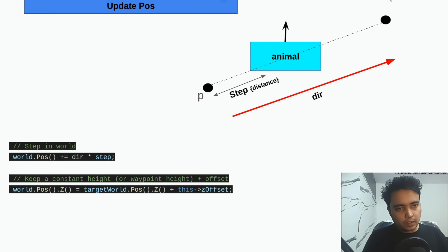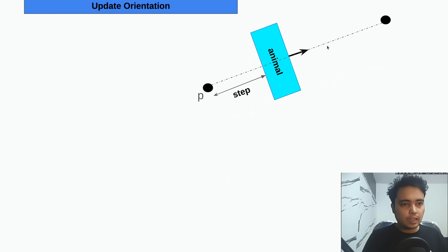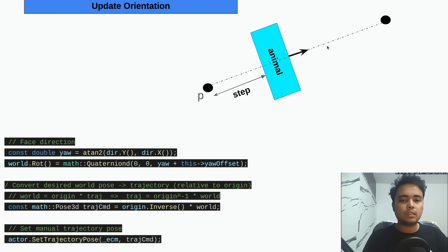Now we have to get the angle as well. How do we get the angle? It's very simple. You do this tan inverse of y by x. So this is what's done over here, and we want it in robotics. Generally we use quaternions, and even Gazebo Sim is going to accept all of your values in quaternion, so that's why we are converting into quaternion form.